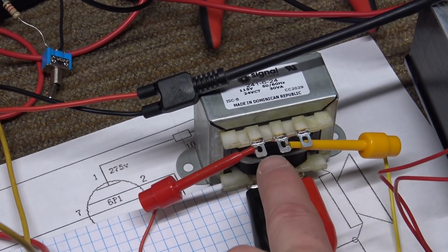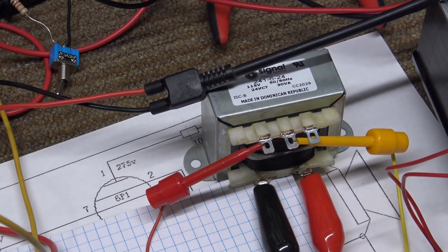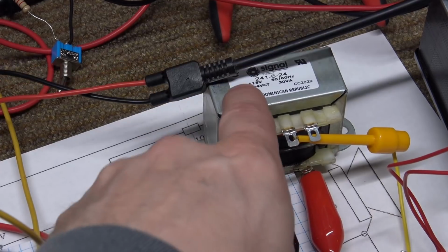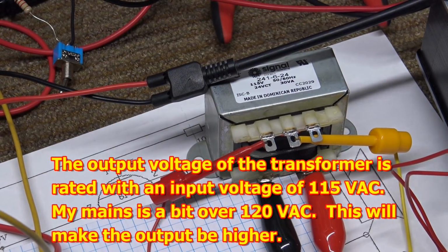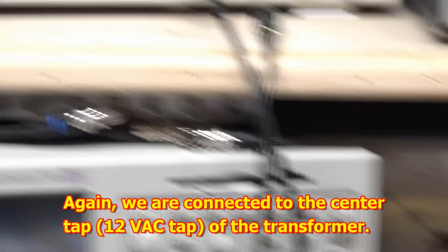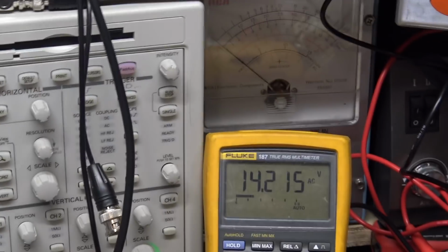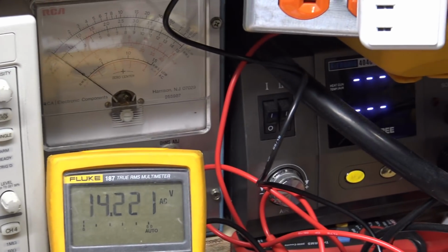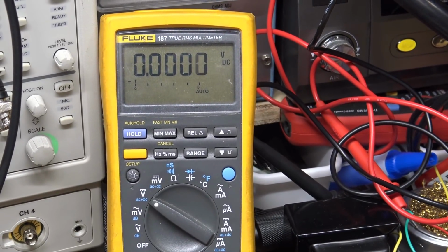So you're reading a little bit high. It should be about 12 volts, but because we don't have much of a load on there, and because we have more than 115 volts, we have 125 volts, we're actually getting more than 24 volts out of the transformer. So that's what you're seeing. So there's your 14 volts. And you can see the oscilloscope agrees with the meter. And if we move the meter to DC, it says there's 0 volts because there is no direct current there. It's alternating.